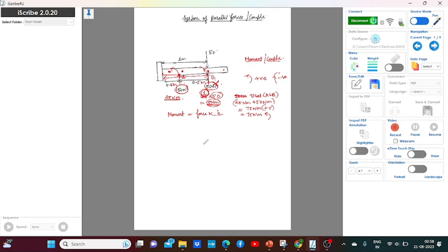Okay, now the force applied by the person on the other side of the door is 50, and the couple applied by this person is 50 into 1 meter. So this person C applies a couple in clockwise direction like this, and clockwise is considered negative. So the rotary movement by this person is 50 into 1, which is nothing but 50 Newton meter.